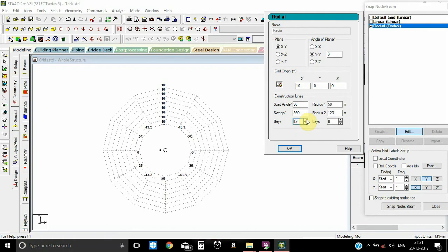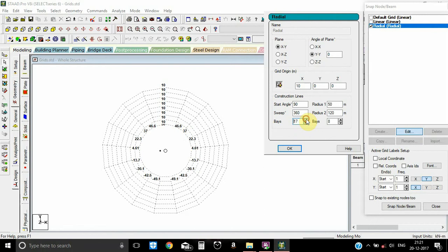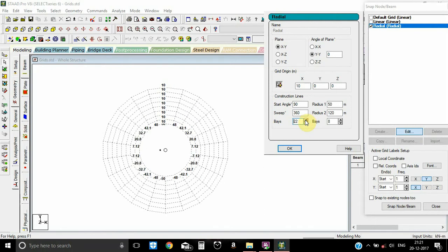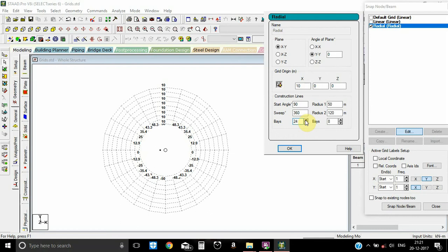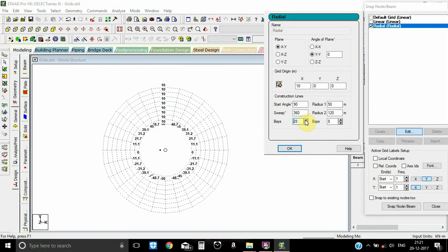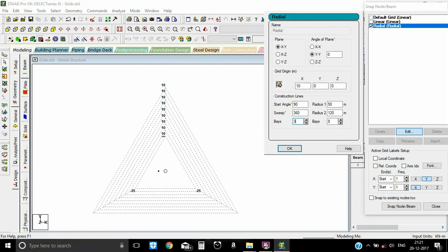Here you guys find a radial line is being added into the radial circle system, radial grid system. So you found the polygonal circle turns into a circular grid system. Yeah, that's good. So this is what will happen when you increase the bays. You can't create fewer than that. The least number of bays is 3.